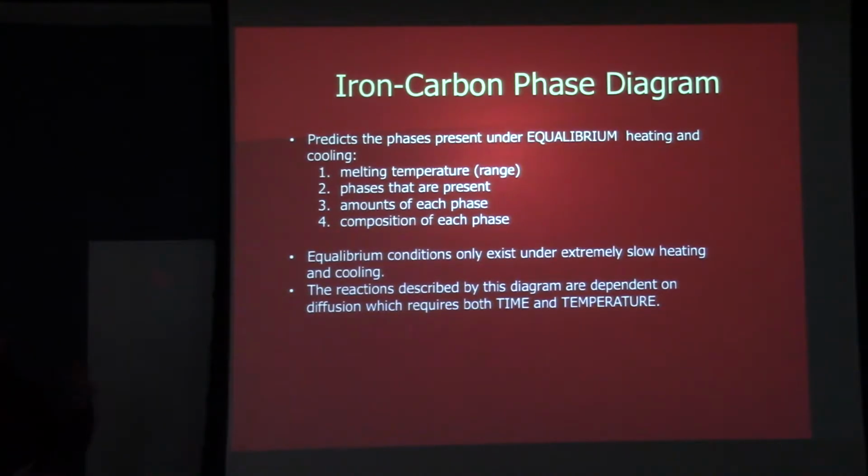It's important that when we say iron-carbon phase diagram, there are two things that we really should say that we don't typically say. First, we should call it the equilibrium iron-carbon phase diagram, and instead of calling it the iron-carbon phase diagram, we should really call it the iron carbide phase diagram, because that's really what's present. It's not typically just plain carbon. It's iron carbide, with the exceptions of when you can generate graphite. But that's not what we use, so we have to all learn what we really mean when we use these phrases. So equilibrium, this is important.